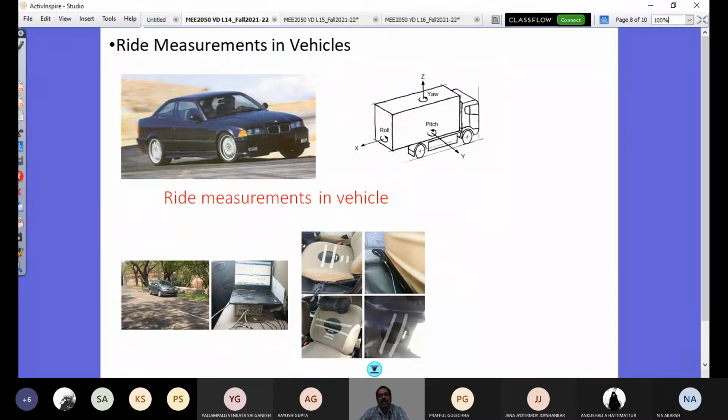We were doing it with the ISO 2631 standard to make measurements in the vehicle at 4 different locations. One at the seat location with 3 accelerometers, to see what the driver actually perceives when you drive this vehicle at different speeds. Another one at the seat rail, so that we will know what is the input that comes to the seat, and that is getting transferred to this occupant. So such sophisticated, advanced, high-end instrumentation and equipment are necessary for whole body vibration of a passenger car.